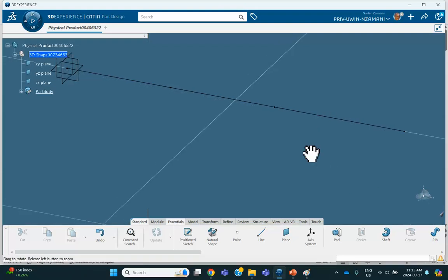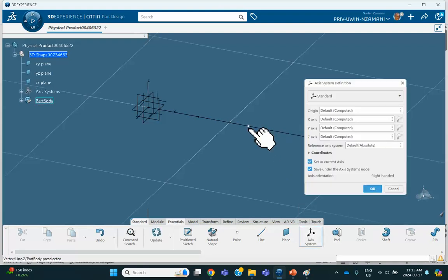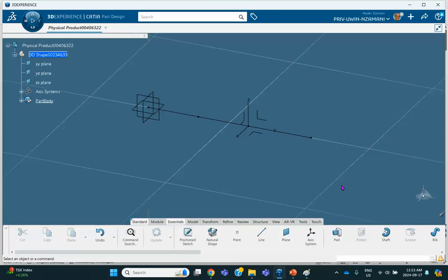Okay, so I've got all these things worked out. Now I'm going to make my coordinate system. As I said, it doesn't matter where you put it. If you want to put it somewhere off, no problem, but I'll put it right where it's supposed to be, right there. So here's the axis system. If you don't do that, at some point you're going to have to come back and create a coordinate system, because for the hinge you have to specify the direction, the axis system.